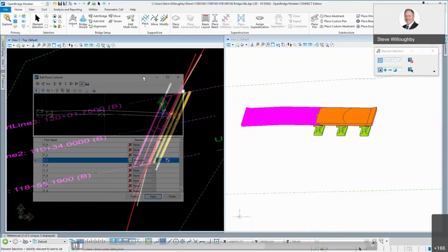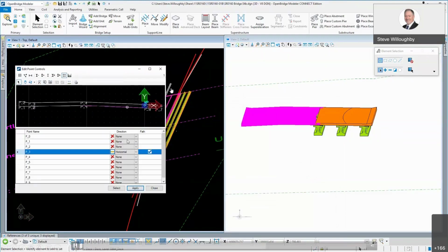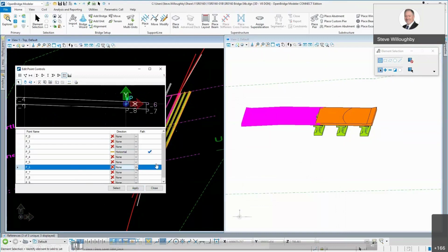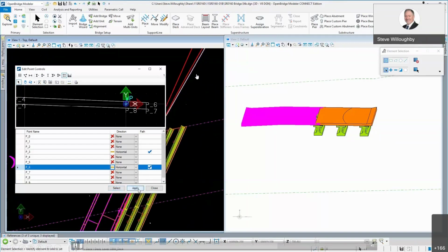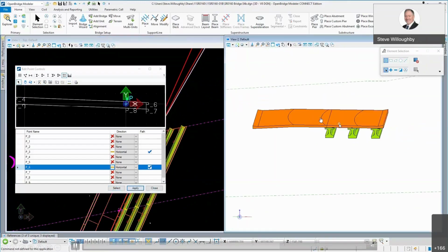But really, again, the key thing is these point control lines that you draw, think of them as being infinite, right? If you remember back to your geometry class back in high school, lines were infinite. And so you have to make sure that these won't cross or force your section to somehow cross some other point, such that maybe 0.6 would end up to the left of 0.5 somehow. So that's why these are extended out and help this work precisely how we want.